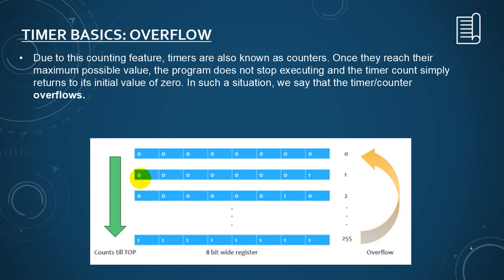Does the carry flag make the count go to 0? No, you see, this is the register that holds the counting. It starts from 0, 1, 2, 3 up to 255. Again 0, 1, 2, 3 up to 255. So when it goes to the top, you set a bit in the flag register. There's a special flag register, not the main flag register. The counter has its own flag register. Okay, we'll discuss that. But by checking the flag register, we know that one count has been made.